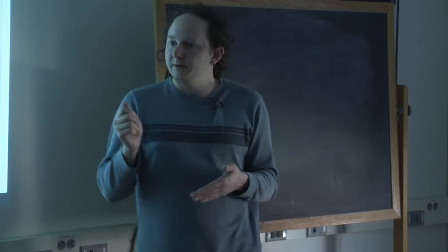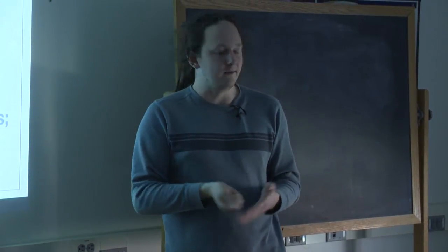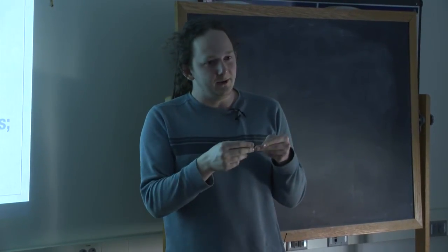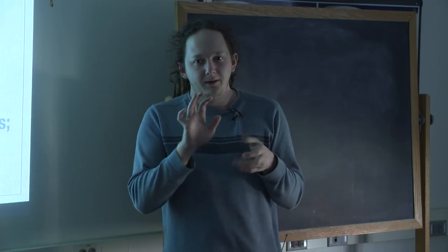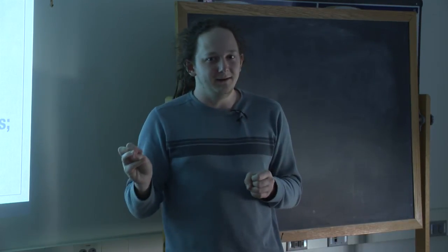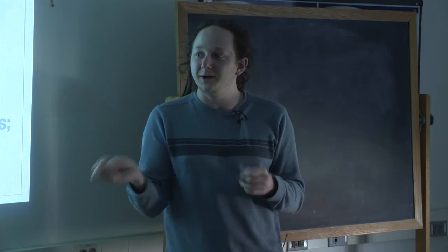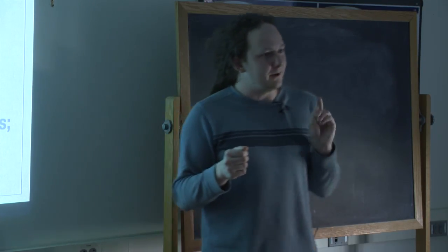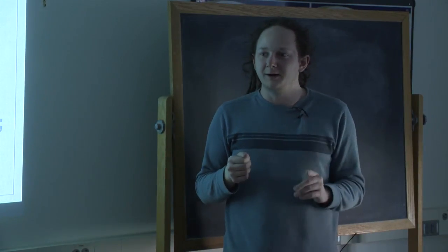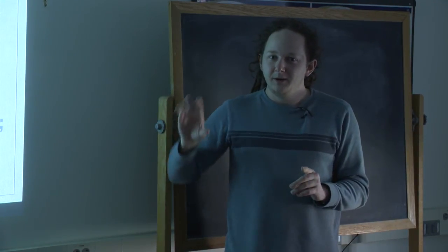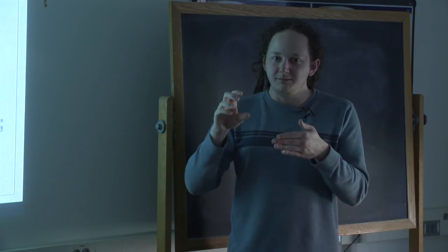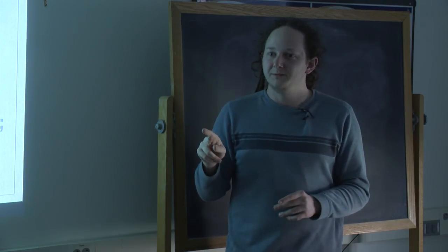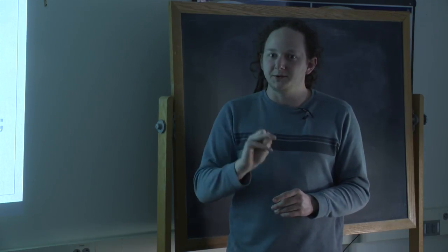So what Andrea Barisani and a colleague of his discovered was that the wire that marks the beginning and the end of the packet is kind of redundant, because you have this other wire that marks where the symbols are valid. So it turns out that in 3/4 of the Ethernet cards on the market, this MAC chip will only pay attention to those first two wires. It ignores the wire that marks where the start and the end are.